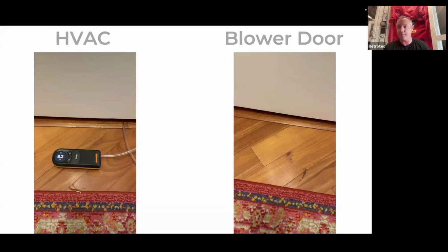And so that's what's happening with that supply air that's being delivered to it. As it gets delivered, it just gets pushed outside. Whatever doesn't come back through that door undercut or any other interstitial leakage, it just gets pushed out. So that's a lot of our conditioned air that we're actively driving to the outdoors. So we can see that with just the HVAC system running, and then we can see that there are also a lot of air leaks for that conditioned air to escape with the blower door and the fogger.